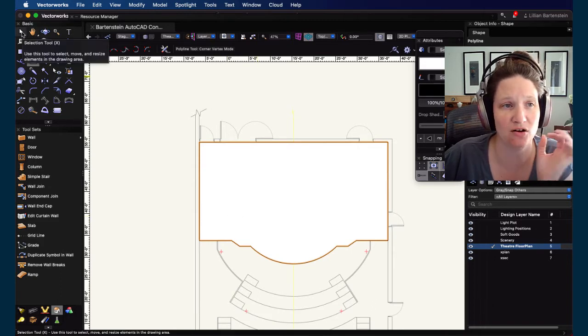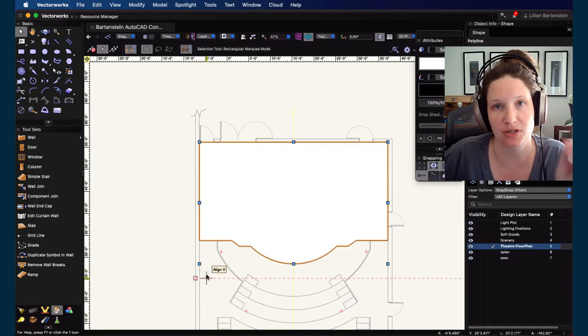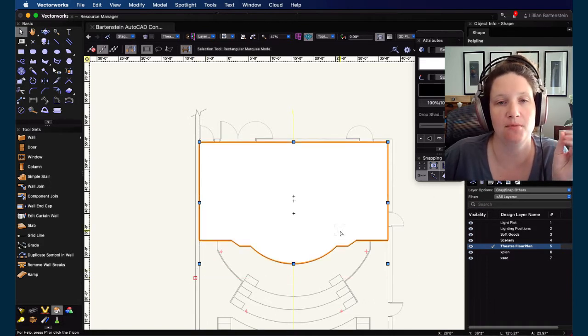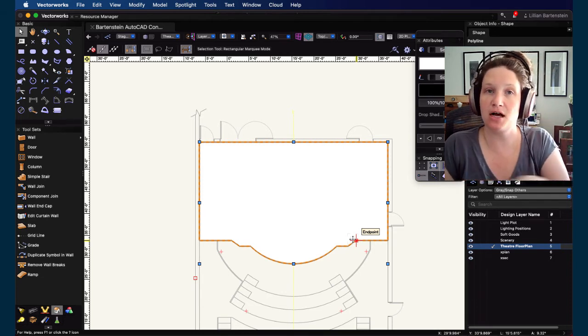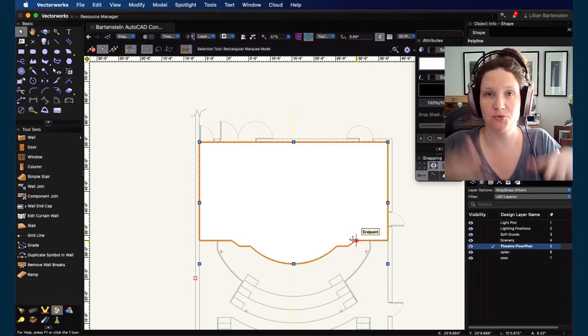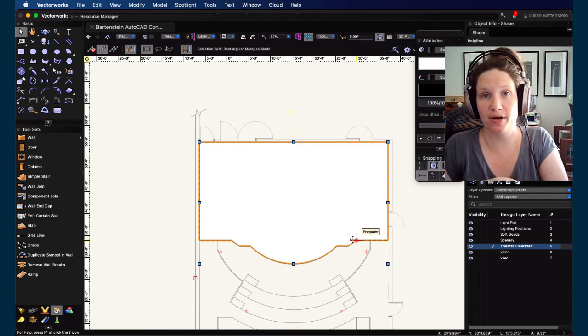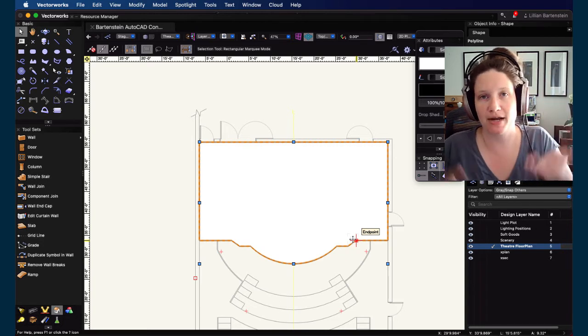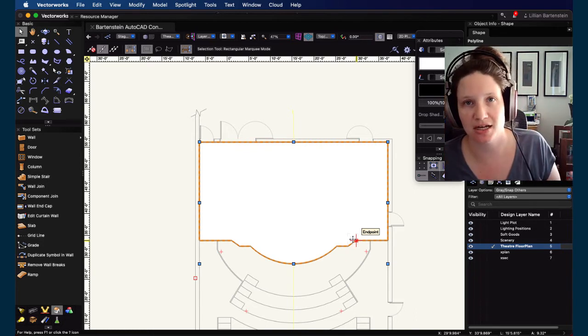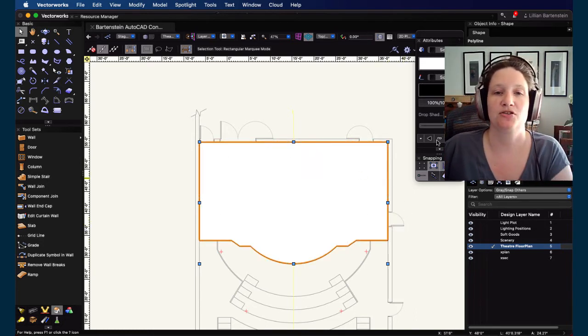We're gonna now actually extrude this shape, and we're gonna extrude it in the negative direction so that at the 0 level of our file is our stage floor. Everything else will be relative to that 0 point. And that's because as I'm drafting scenery, I wanna be able to just set things on the 0 line. I don't wanna have to like raise them up to be sitting on top of the stage as I draw. So I'm gonna start with this shape.